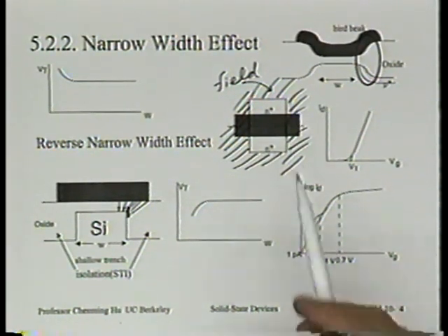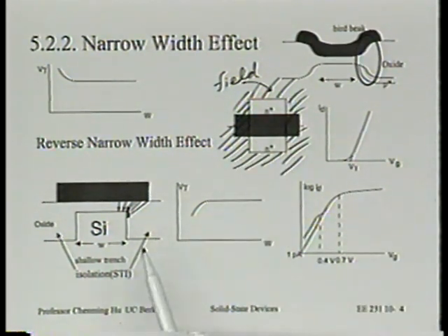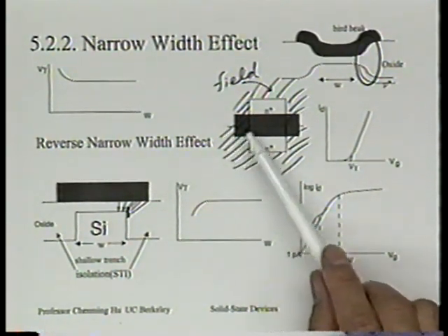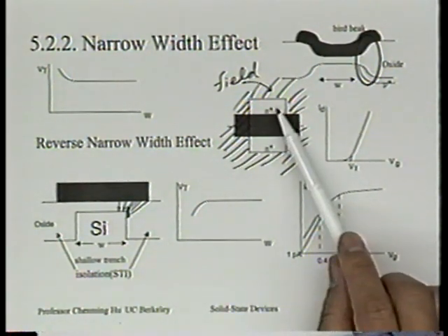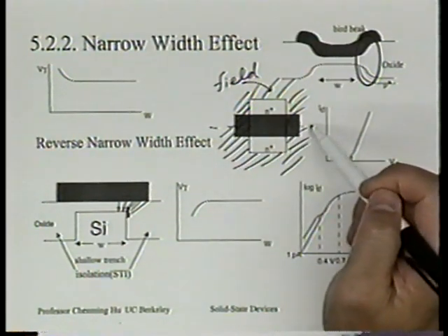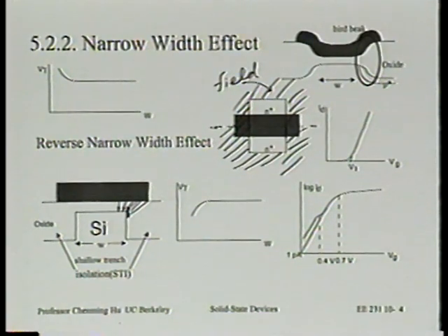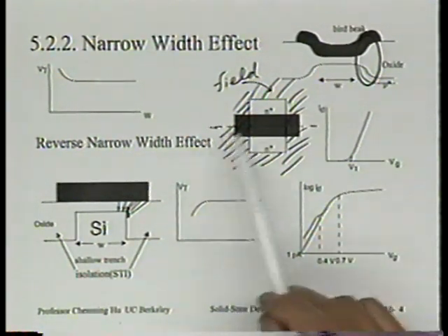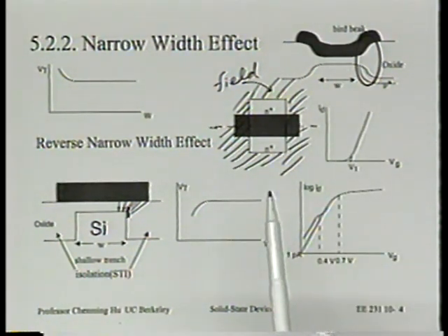All right. So enclosed by the field region is this active region. And the active region is further divided into 3 parts. One part is the channel that's covered by this polysilicon gate. The 2 other regions are the source and drain regions. Okay, is this picture clear? All right. Next, let's think about the dotted line across this transistor through the middle of the polysilicon gate. Now, if we draw the cross section along that plane, this is what you see. Let's visualize this. Okay, feel comfortable with that. All right.